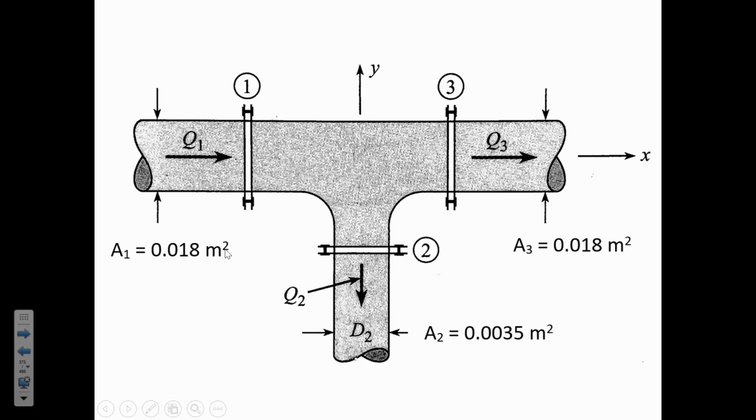This is the tricky one. This combines some of the ideas that we addressed with the black box problem today. So this is a combination of the black box, but then there's also the pressure times area thing happening, because these pipes continue. I think the drawing is implying that the pipes continue with that kind of curved shape, that means that the pipe continues. So there's water coming in at 1, going out at 3, and the rest of it's going out at 2. So you're going to use the continuity relationship to find out the in equaling the out.